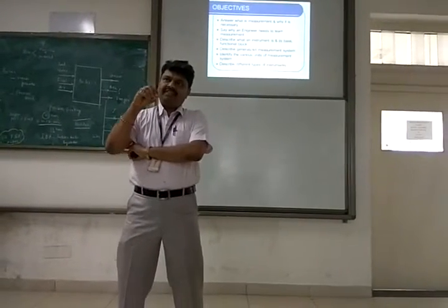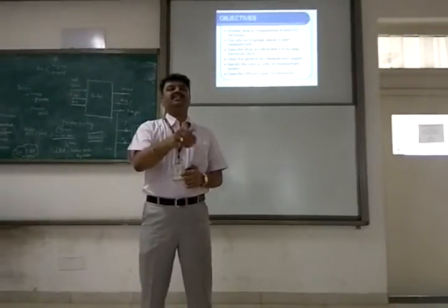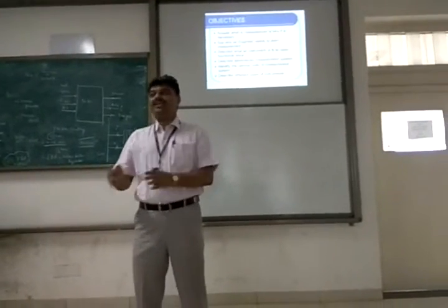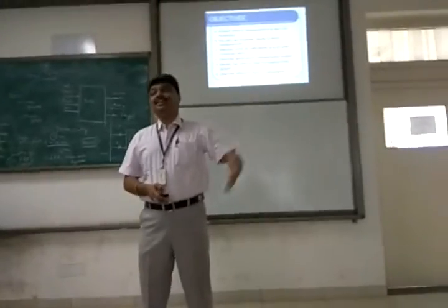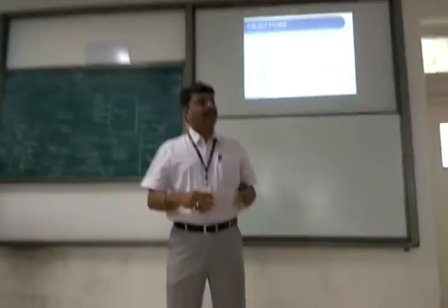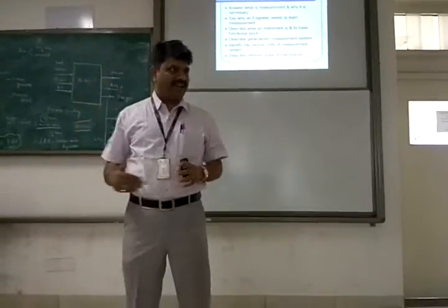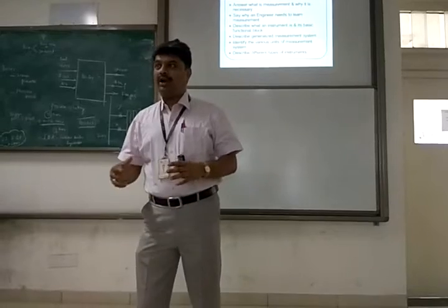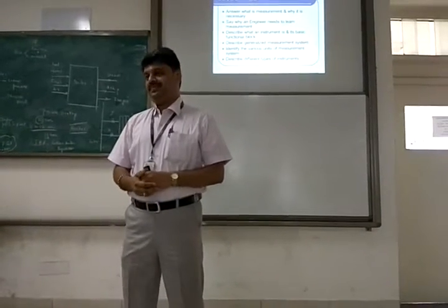So one form of signal to another form of signal, you call it a transducer. To be very precise, it's not one form of energy to another form of energy. For example, even a fan, we will not call it a transducer. Why? It doesn't convey any meaning. It converts electrical energy to mechanical energy, but we will not call a fan a transducer. We call a fan a machine.